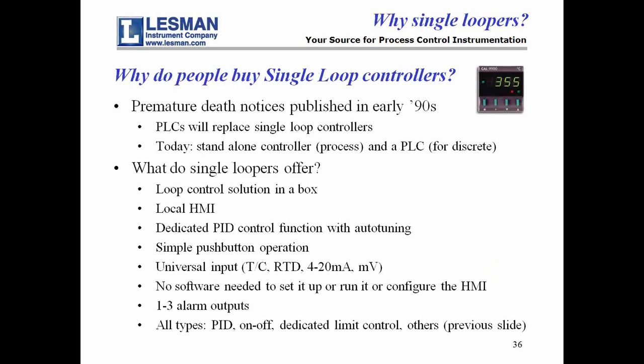So in general, people say, well, why do people buy single loop controllers? Again, there were death notices published in the trade journals in the early 1990s saying PLCs are going to replace single loop controllers. And yet today, even with the people that use PLCs, we frequently walk in and see that they're doing pressure and temperature control with modulating outputs with standalone temperature controllers or single loop controllers, and they'll feed that data back into the PLC so the PLC knows what those conditions are, but then they do other discrete operations in the PLC.